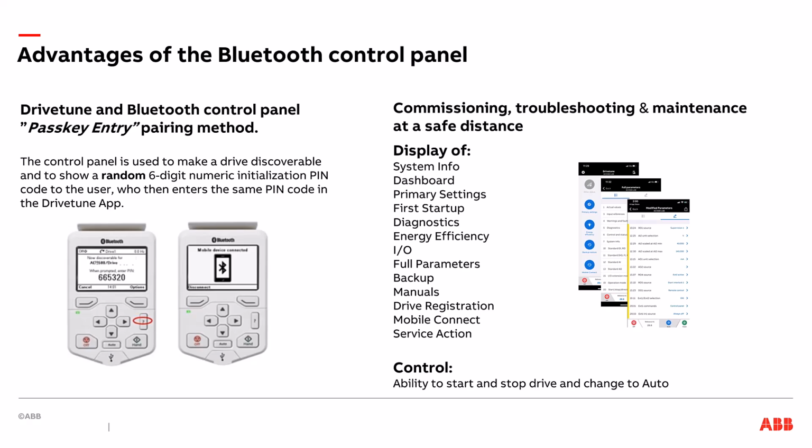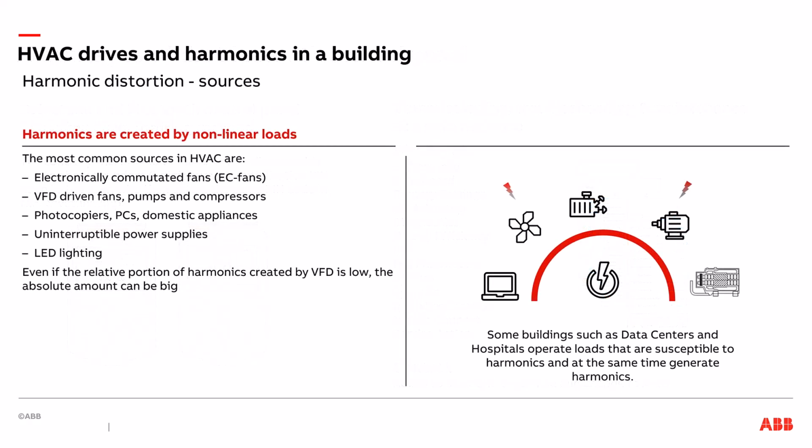Harmonics are an important topic to consider when looking at drive selection for any installation that has sensitive equipment. This includes medical equipment, airport electronics, security systems, communication equipment, and laboratory research equipment. Harmonics can cause interference to electronics that have carrier signals, such as lighting systems and power meters. Generators may have voltage regulator issues when loaded with high harmonic content.